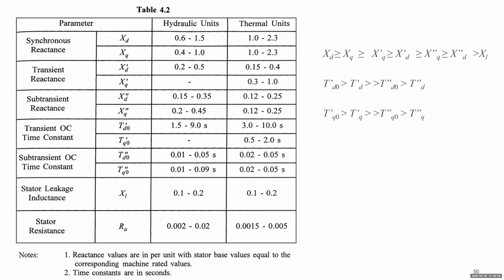Also, for instance, if you have a power system model where every generator is a thermal unit, which is a round rotor generator, but you want to assume one region to be a hydro power plant, you definitely cannot use a thermal unit. You need to change it to a hydraulic unit. When you change to a hydraulic unit, you can use this table to create another set of data, because the D axis and Q axis are not fully symmetric anymore.